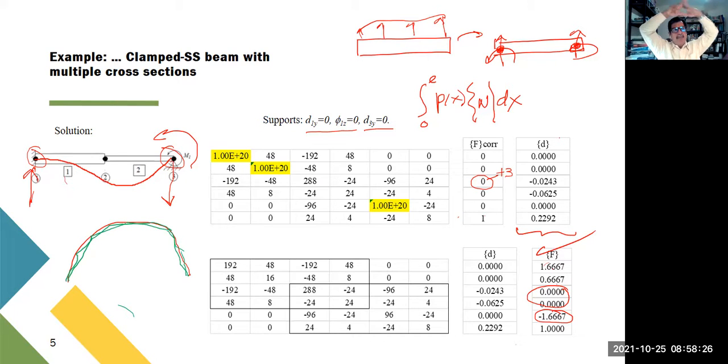If you have a P of X integrated, it will give you maybe a fourth order, fifth order polynomial. That's for the exact solution. Using little cubics, you can approximate the exact solution. If you have doubts, you have to include one more joint and compare.